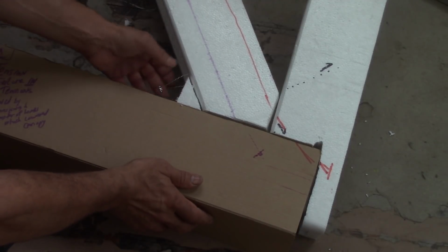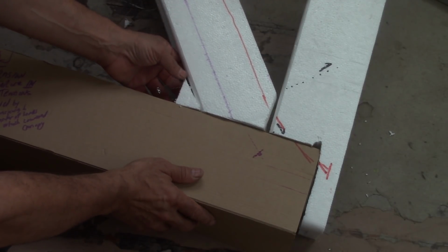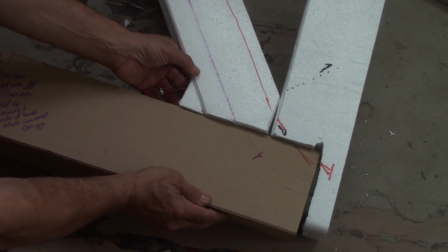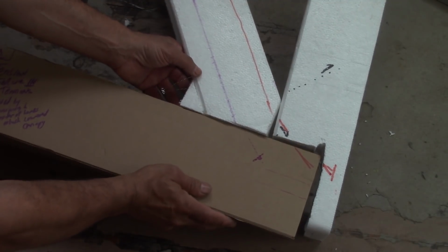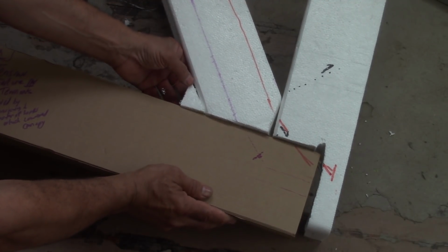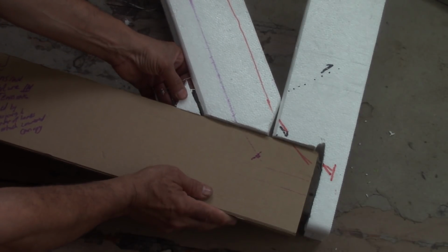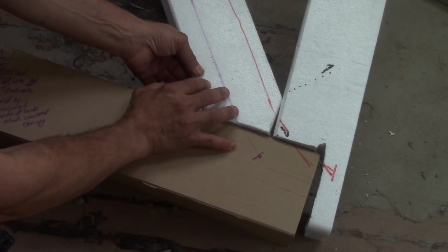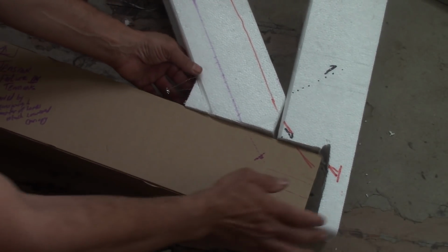This first crack is very important. This is where the bridge dipped down just a little bit. Watch it again. It opens at the top. So it's concrete. It's still connected at the deck here. And as this creeps down, that's your opening. I'm exaggerating now. That's your opening. That's how you explain that little chamfer's opening initially.